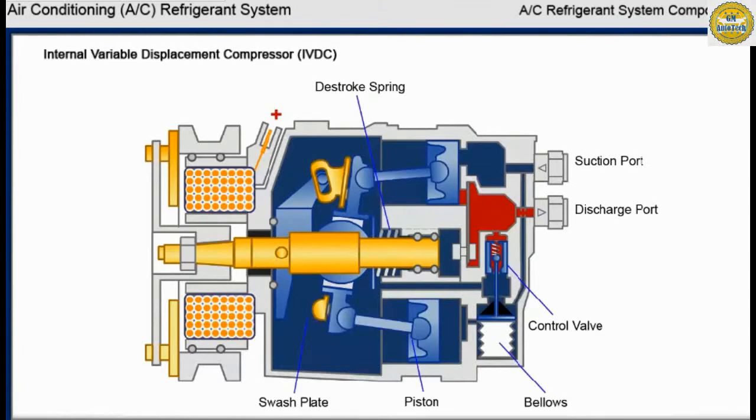When re-engagement occurs, fuel economy is improved due to lower compressor displacement, with reduced torque, also resulting in reduced clutch noise. The IVDC has a higher ability to compensate for refrigerant flow restrictions, which causes diagnosis to be different from other piston and scroll-type compressors.